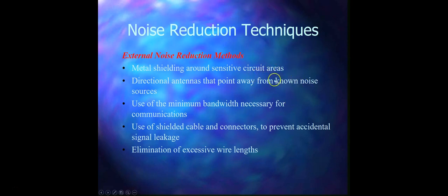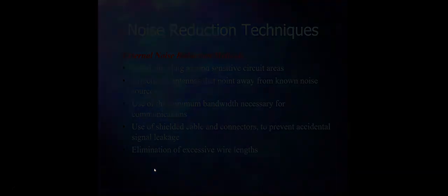Metal sheeting around the sensitive circuit, same thing. Directional antennas that point away from the known noise sources, use of the minimum bandwidth necessary for the communications, use of shielded cable and connectors to prevent accidental signal leakage, elimination of excess wire length.